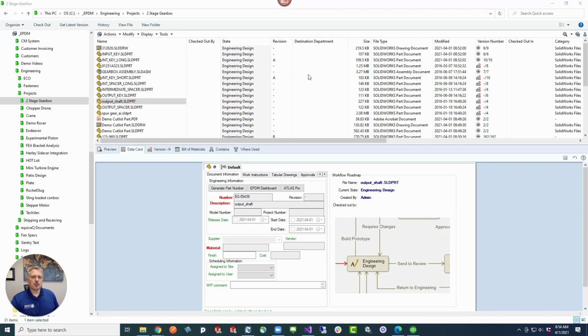So this Q-tip assumes that your revisions are being managed by the workflow, and that means that you're not doing a right click on the file and going up to modify and then set revision. The set revision is sort of a special command because it's intended so that you can do your releases without actually using the workflow. You can just use one state and then just stamp your revs whenever you're ready.